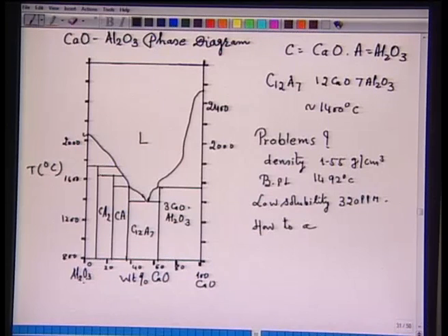How to add? It is added in the form of alloys: calcium silicide, calcium iron, calcium aluminum. Rather, it is added in a wire form, a cored wire filled with calcium silicide, and these wires are available in the form of a roll. This calcium silicide powder is injected at a very high speed, varying from 30 meters per minute to 300 meters per minute, so that it directly enters deep